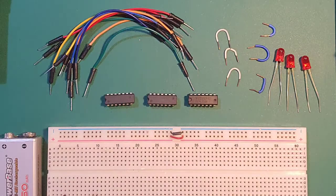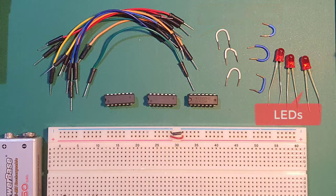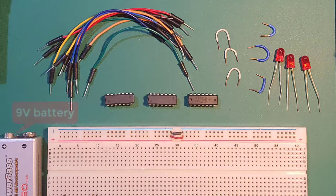In this activity, we will be needing the following materials: a breadboard and a couple of connecting wires, 3 LEDs, the 7408, 7432, and 7404 logical AND, OR, and NOT IC packages respectively. We also need a 5-volt power supply. You can use either a 9-volt battery, your Arduino board, or your cell phone charger.